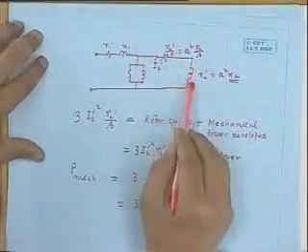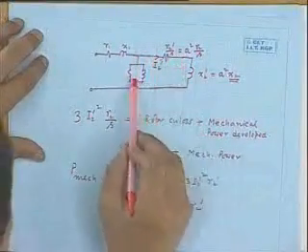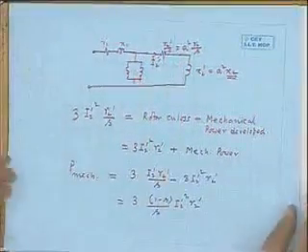Very close to synchronous speed, but not synchronous speed, running below. See, ideally, if it could run right at synchronous speed, what would have been the value of S? 0. And if S is 0, then this branch would have been an open circuit. And you could perhaps measure RC extent. Anyway, today I stop here, and next time I